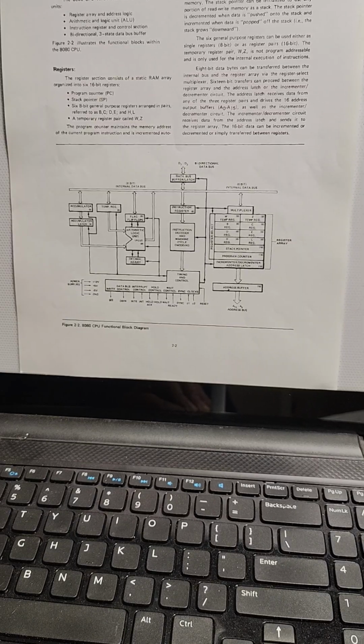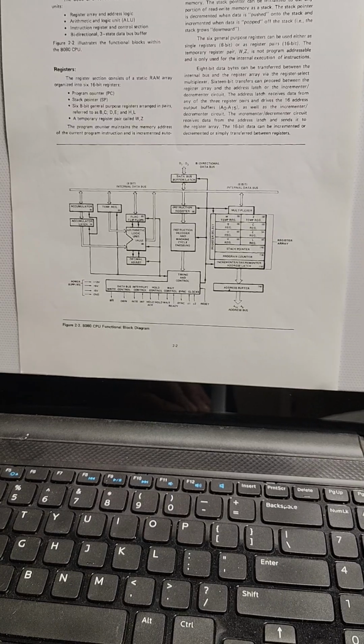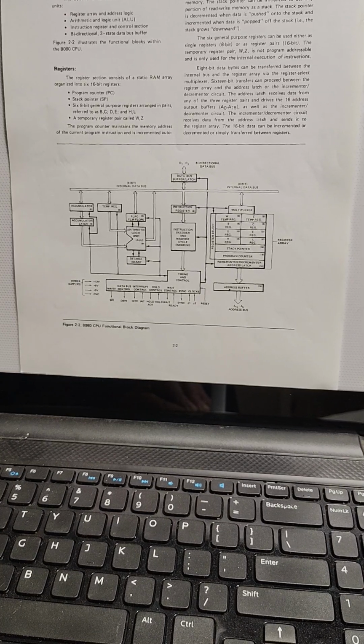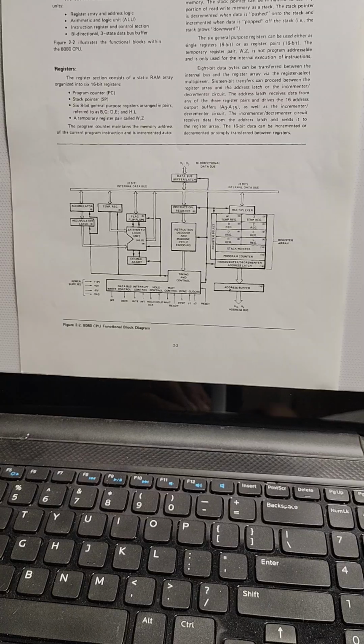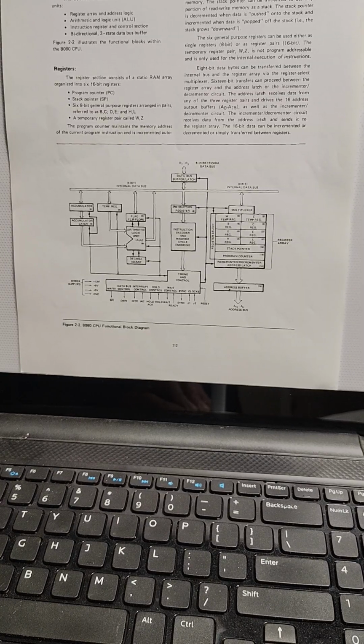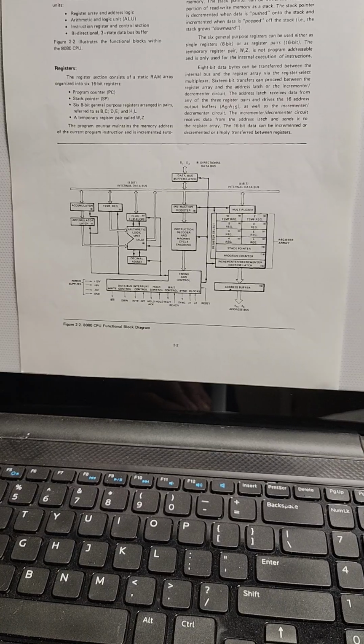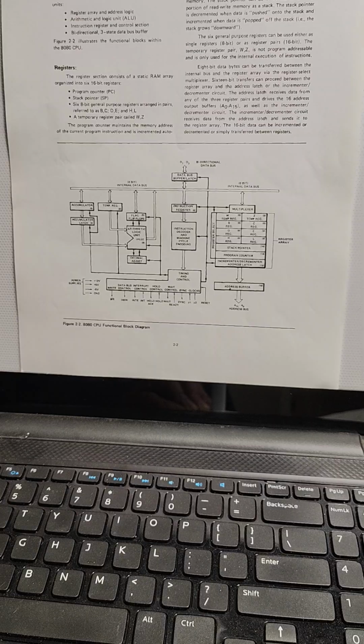The 8080 uses isolated I/O, uses in and out instructions, so you can address 256 input and 256 output ports separately from the memory space. Control signals, there's read, write, I/O, and memory to differentiate between memory and I/O accesses. A ready line for wait state insertion to synchronize with slower peripherals and such. And then an address latch enable for demuxing address and data bus.